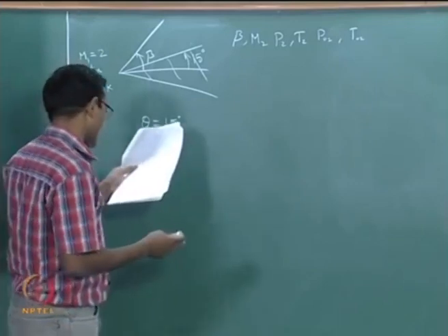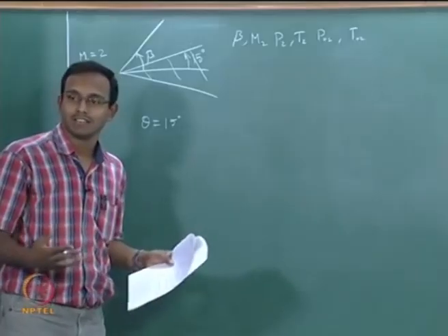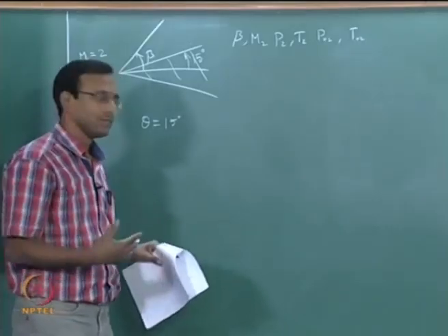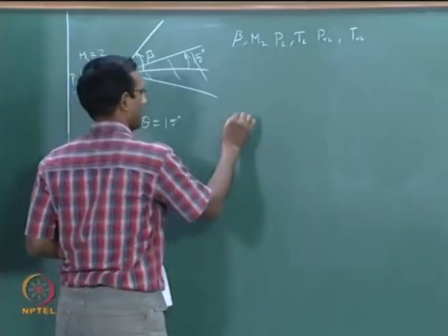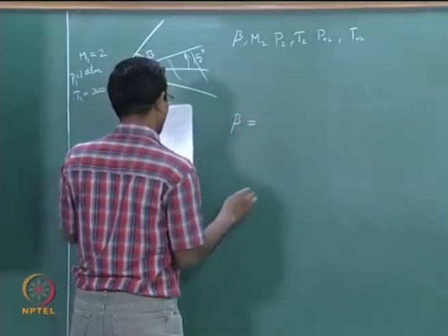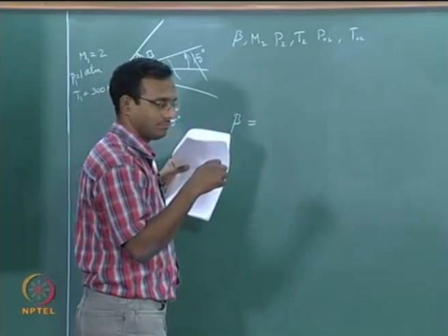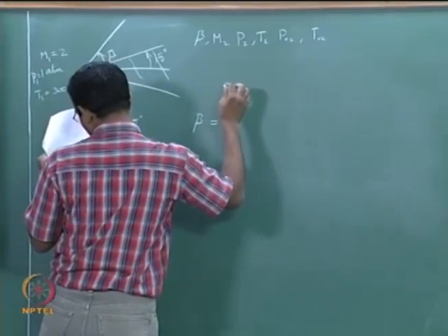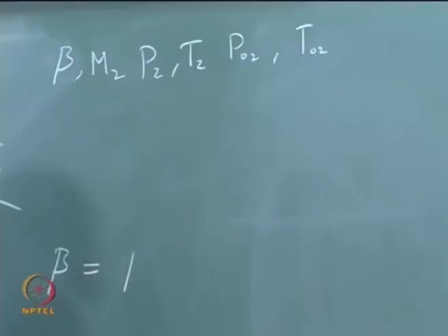If I look at the charts, I have gas tables which give you, for a particular Mach number and a given deflection, the beta value, or you can just use the chart. I typically use the plot, even though I have the table. I go look at that, and I am getting beta value to be 45.